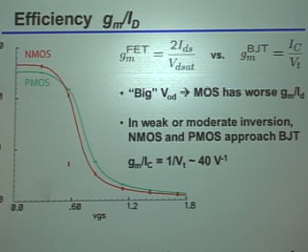Yeah, the speed is different, right? So in other words, even if I have the same transconductance efficiency, the parasitics I'm going to get, at least typically from the PMOS, are going to be worse than the parasitics I get from the NMOS. Now, by the way, I said typically because if you go to some of the super modern advanced technologies, the way things are scaling, or at least the way people are engineering the devices, is such that the PMOS devices may soon actually be faster than the NMOS devices.